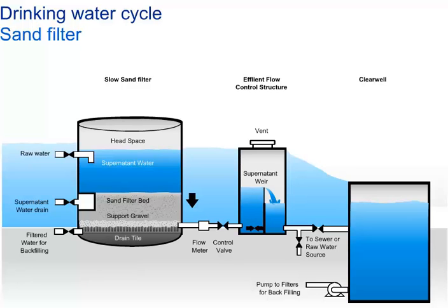Effective filtration extends into the depth of the filter. This property of the filter is key to its operation. If the top layer of sand were to block all the particles, the filter would quickly clog. To clean the filter, water is passed quickly upward through the filter, opposite the normal direction, called backwashing, to remove embedded particles. Prior to this, compressed air may be blown up through the bottom of the filter to break up the compacted filter media to aid the backwashing process. This is known as air scouring.